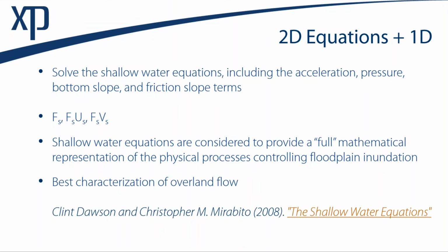So then we have to link those in time. At each time step, our 1D channel model, our 1D stormwater model, and our 2D model can be exchanging flow with each other based on the things we've talked about already. The 2D terrain: is there capacity in the network? Is my 2D model returning flow to the 1D model? Or is my 1D model still surcharging and delivering flow to the 2D terrain? These have to be linked in time, so at each time step, you have to have the ability to accurately exchange flow between the three different types of models that I just described.